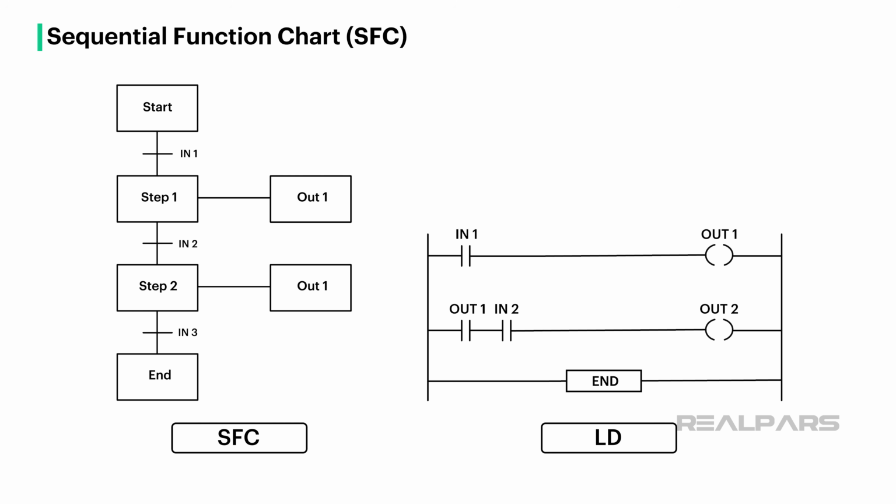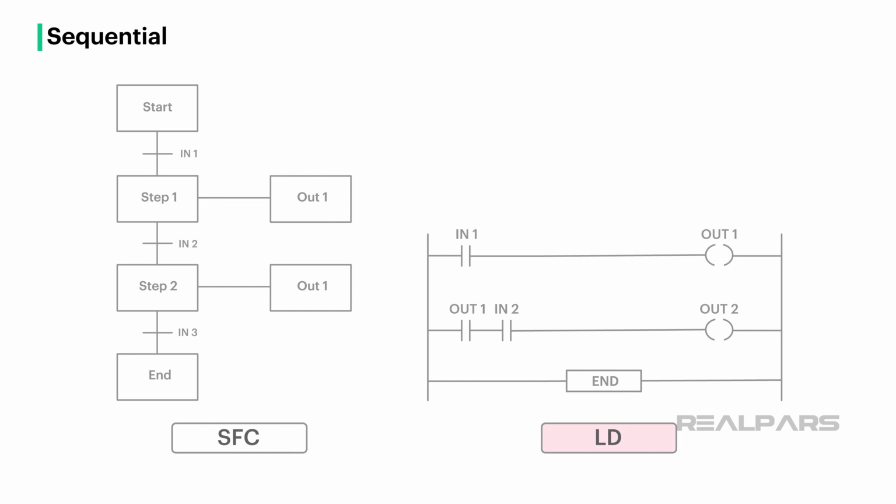Since SFC is used for a different purpose, it shouldn't be compared to ladder diagram. Instead, you can think of it as a complementary programming language that you can use for sequential processes. You can model the process in SFC and then implement the control logic in ladder diagram.